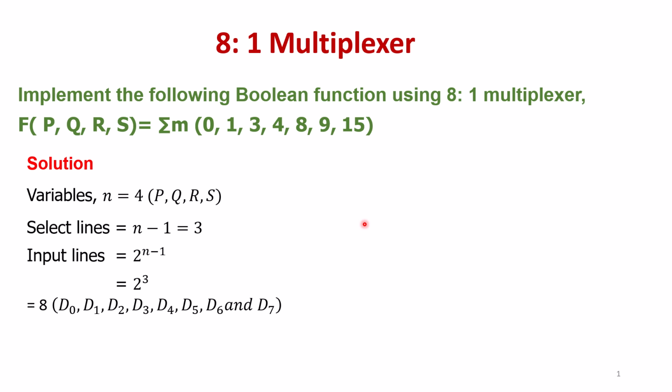A mux is a combinational circuit with more than one input line, one output line, and more than one select lines. What it does is, a mux selects binary information present from one of many inputs, depending upon the logic status of the select inputs, and routes it to the output line. Normally there are 2 power n input lines, n select lines, or you can say n control lines, and one output line. These n select lines have bit combinations that determine which input is selected.